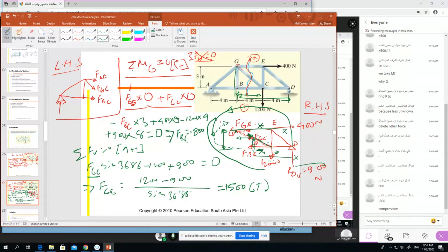When it is minus, you write the answer like this, 800. And at the same time you must change the direction, otherwise you are going to make a mistake, right? You must change the direction, okay, like this. So do two things together. You change the direction, and here you write plus 800 and compression. Now, is everyone clear? So how did we get the BC? So the BC result is this, right? So now we got the BC result correct.